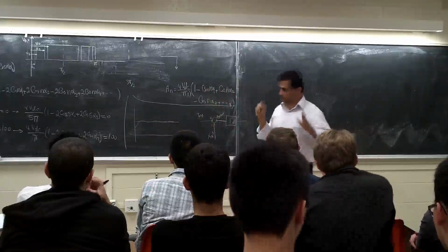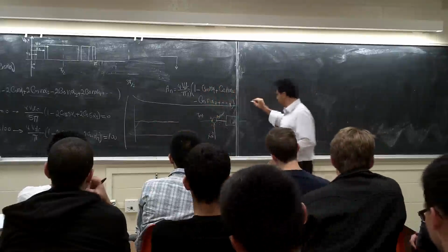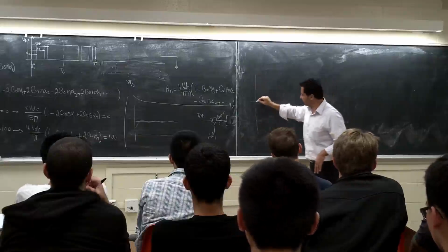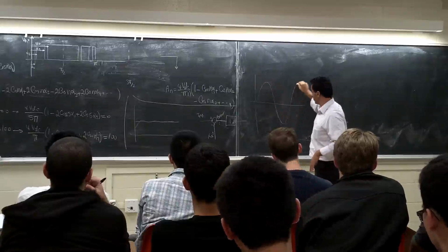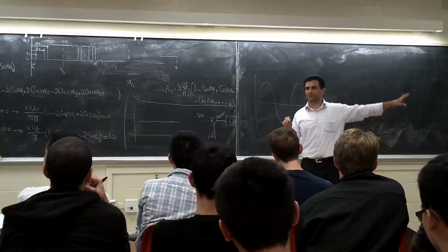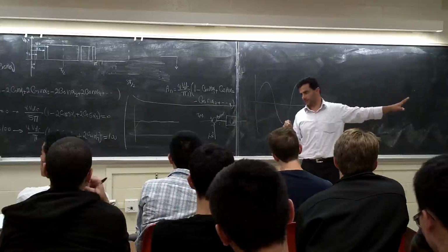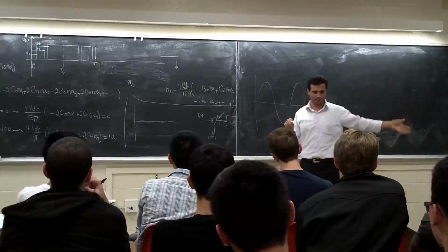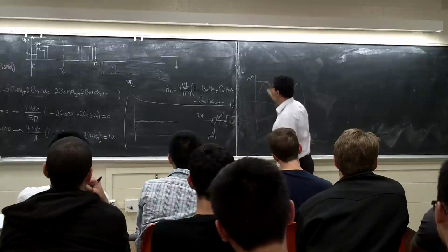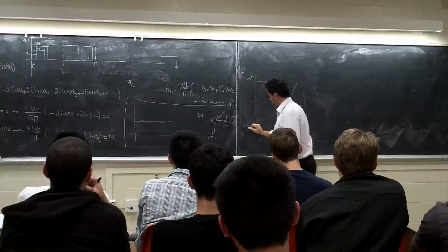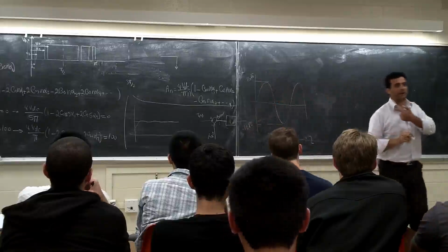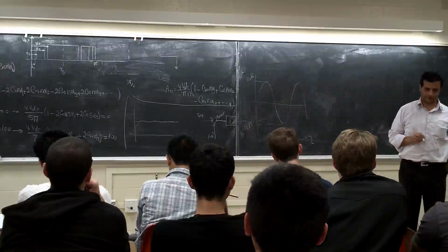I want to design a system with a reference value, which could be my voltage or my current. For example, I want to build an inverter to give me a fixed 110 volt output voltage. This is the inverter, like we'd use in a UPS. 110 volt means 110 square root of 2 peak, with a frequency of 60 Hz. This is my reference.